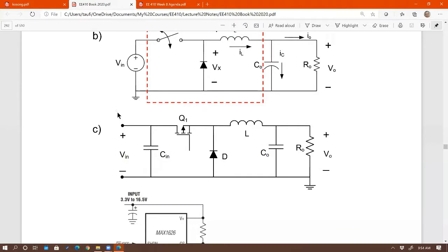So then, because in the real world we're dealing with a non-ideal voltage source, you need this input capacitance. You must have this. If you look at any DC to DC converter in the real world, it will have this input capacitor. It will not work without it. The reason is that this is a high switching frequency circuit, so for high switching energy, the real-world source will not be able to keep up. It would require help from an energy storage component.